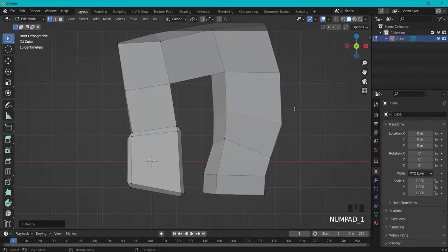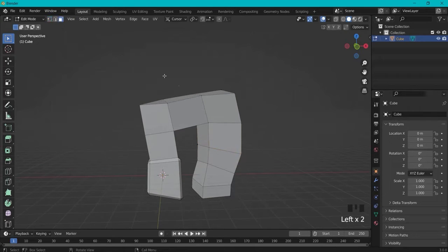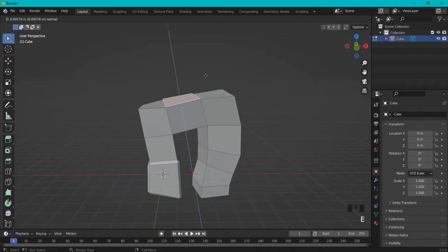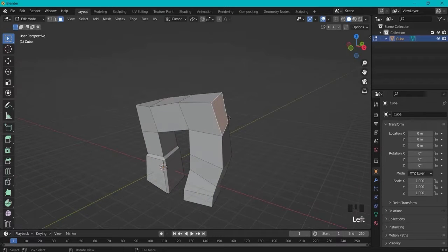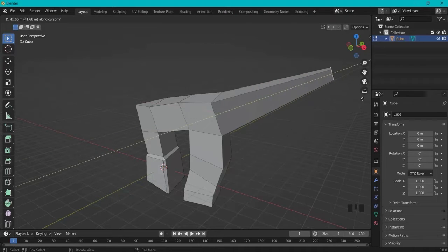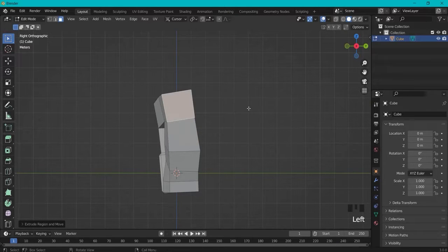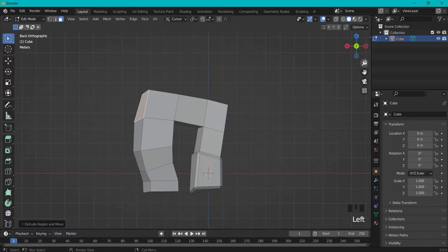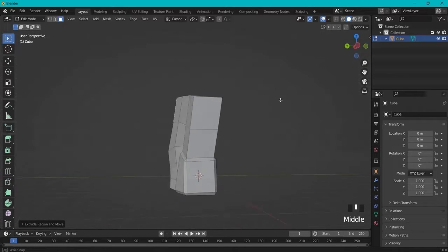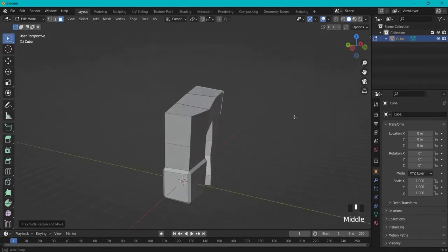By the way, you can also extrude, scale, rotate around a certain axis. So for example, let's go back into face mode. Now hit E to extrude and hit Z. It goes in the Z axis, which is up. Or I can also E to extrude, but then X on the X axis, Y on the Y axis. And you can also see these axes right here. So the X axis is the red line right here, the Y axis, and the Z is from top to bottom like this. So this also works with extruding, scaling, turning around, grabbing, and everything that you would need.